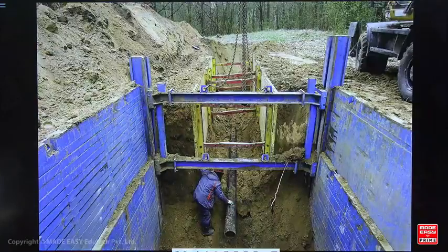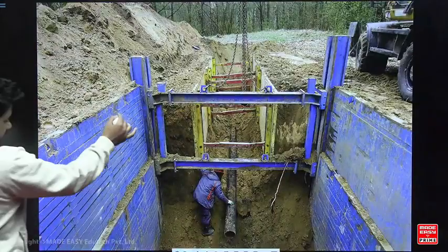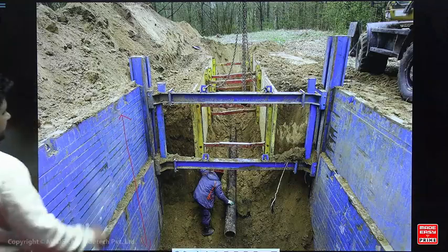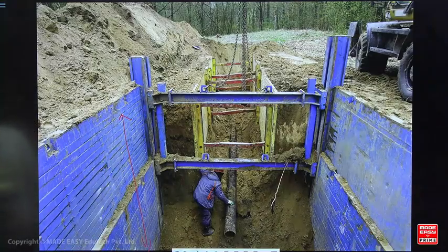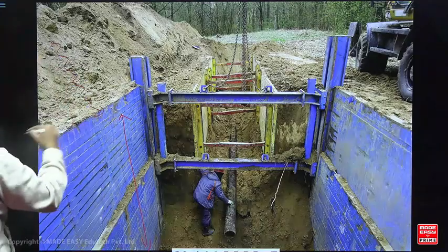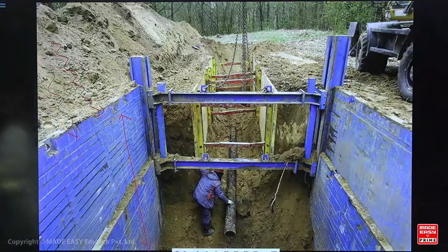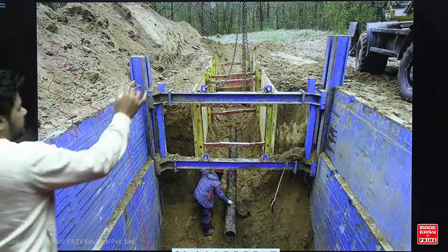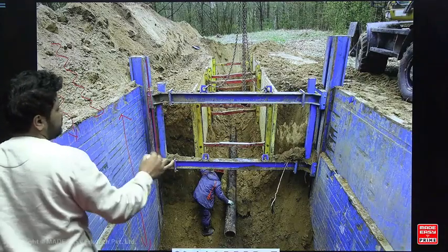And this is called shielding. Shielding में क्या? You can see the depth, you can check it. It is very deep. That means the worker is working at a great depth, right? So obviously there is a possibility that this soil will fall, isn't it? So if the worker has to work, what will they do? They will use planks over here.